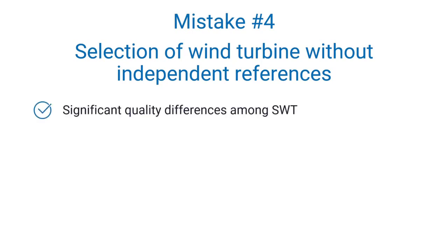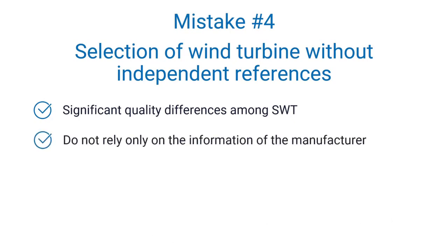Now the last common mistake I would like to mention, and this is selecting a wind turbine without checking independent references. Evaluating the market for small wind turbines, one conclusion is there are significant differences in the quality of the wind turbines. There are many manufacturers with good and proven quality, but the flip side, there is also lots of low quality in the market. Do not rely only on the information of the manufacturer and its sales partners. You have to check independent references.